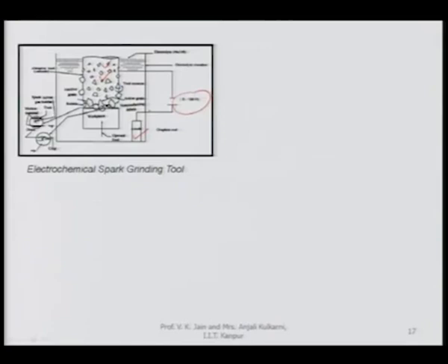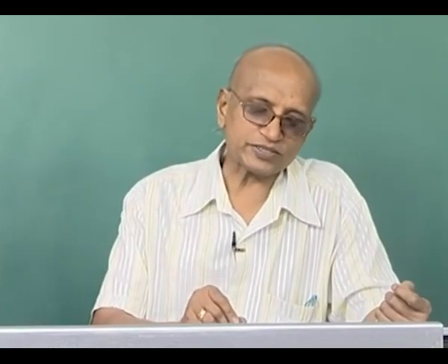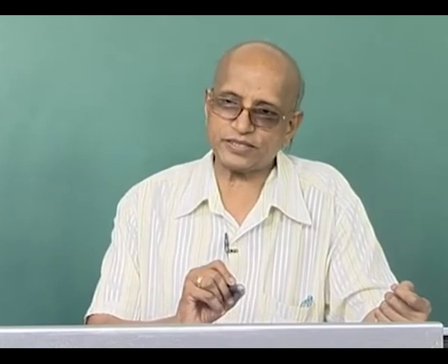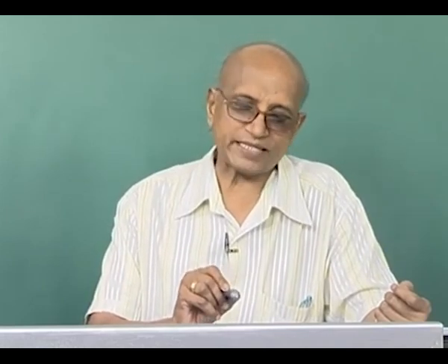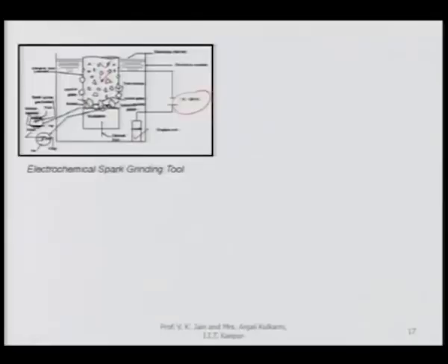As a result of that, hydrogen bubble is formed on the metallic part of the tool. So, that metallic part of the tool where hydrogen bubble is forming, that sparking takes place, and the spark softens the workpiece surface, and part of the material is removed due to sparking, and some part of the material is removed due to the grinding process, because abrasive particles are also in contact with the workpiece surface, and when you are rotating the tool, then this is removing the material due to grinding process or with the help of the abrasive particles which are protruding outside, as well as due to the spark.